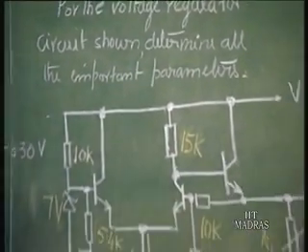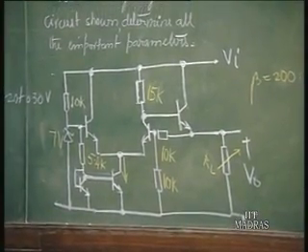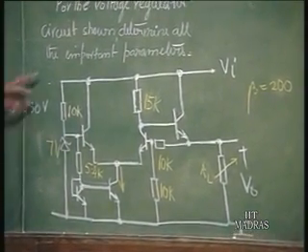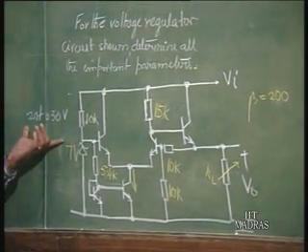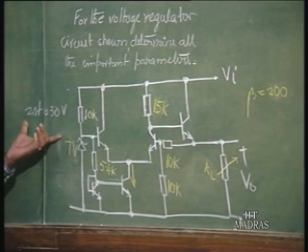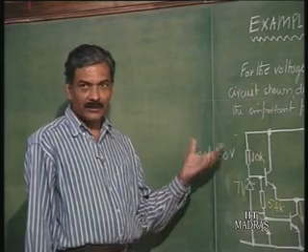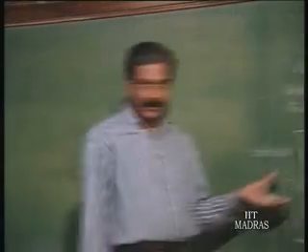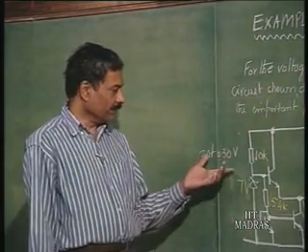So, this is very illustrative of what exactly happens in a typical voltage regulator circuit. Vi is the applied unregulated voltage, which is, let us say, changing from 20 to 30 volts. This is the typical variation possible, because normally this unregulated voltage is derived from the power line, and that much variation occurs in the power line, and you are deriving from transformer, rectifier, filter, an unregulated voltage which is going to supply to this. So, that is varying from 20 to 30.